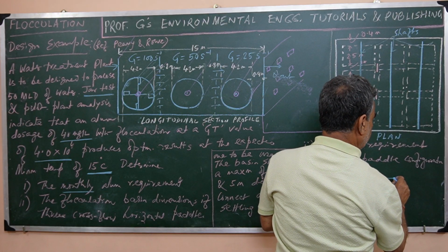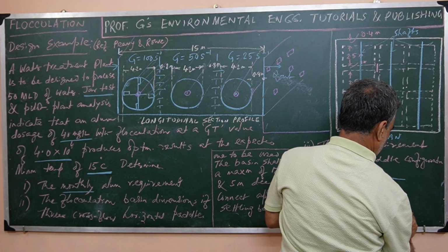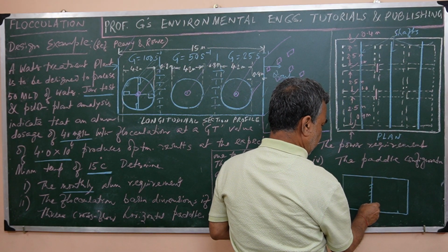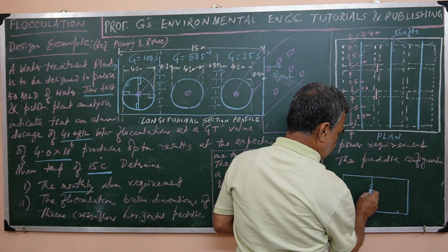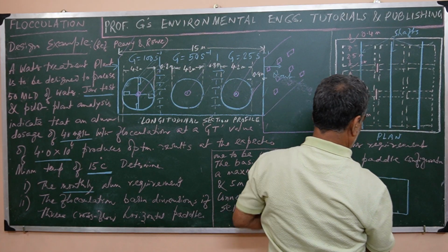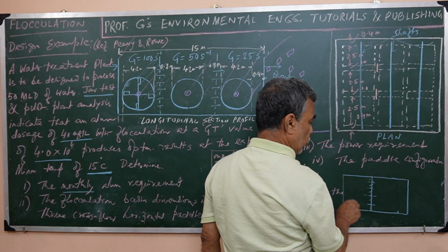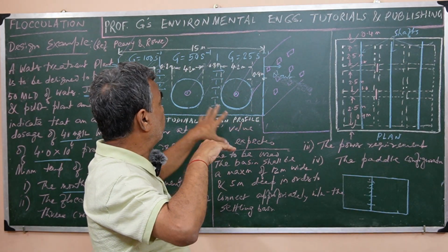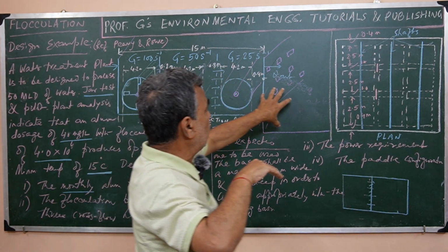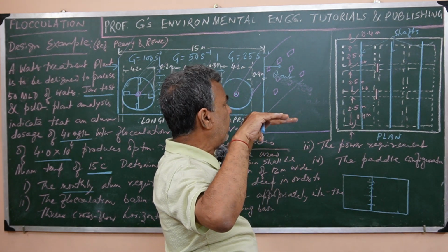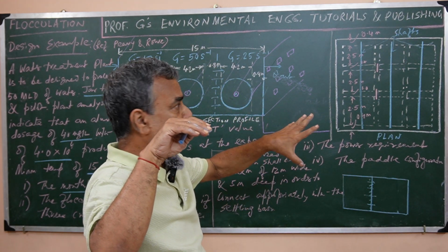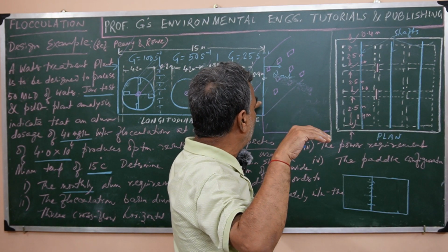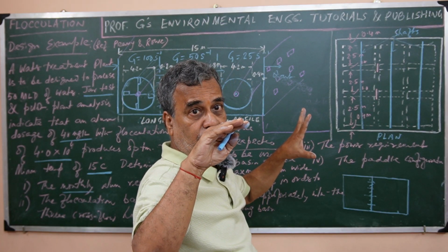This may have a longer or larger length also, right? But this is a common wall, as you see here, so that the water passes through perforations, as I have drawn. So on the common wall, the perforations are there, orifices, right? So it is going like that. So the water will be moving from the flocculation basin to the settling basin, so that under very quiet and quiescent conditions, the settling takes place. In a settling tank, the flocculated water should not be disturbed much, right?